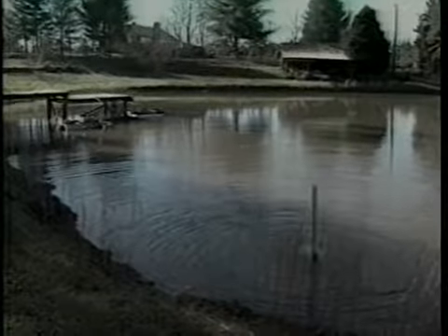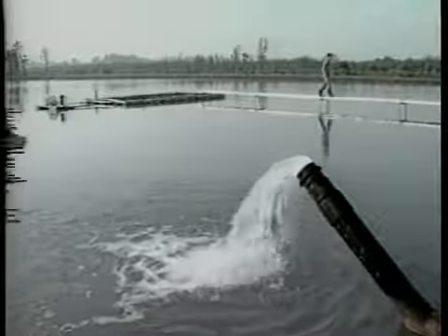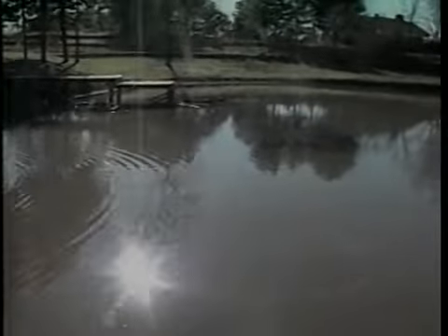If well water high in carbon dioxide is pumped directly into the pond, carbon dioxide levels may increase. Ideally, a spray valve or other device should be placed on the wellhead to allow water to spray and lose carbon dioxide. Fish can tolerate relatively high concentration of carbon dioxide, but tolerance is reduced in the presence of low oxygen. Also, during periods of high carbon dioxide, the pH is usually low.